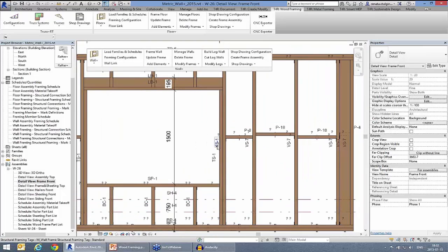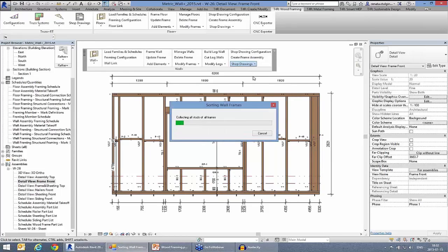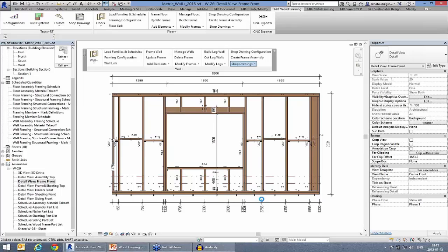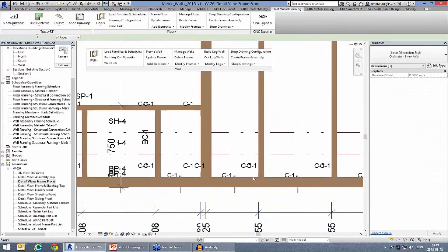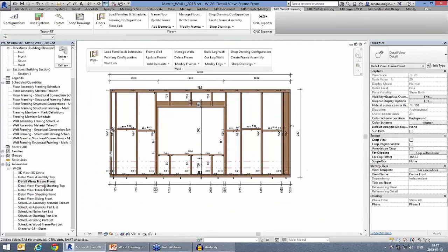It comes from configuration. So for example, this one is a king stud 1, then the vertical stud 7. So the tool will renumber elements according to their type and length. Then we can renumber connections also, because as you can see we have many connections and the additional service holes and the bolts, so also it could be renumbered.